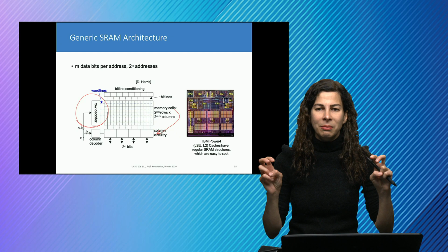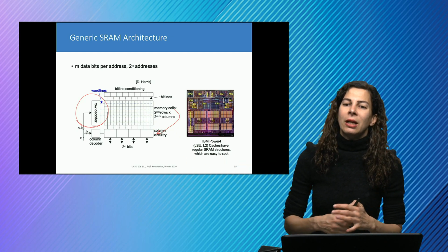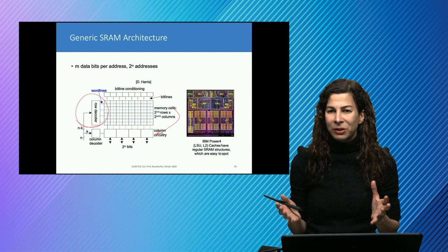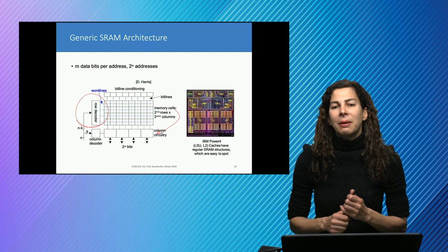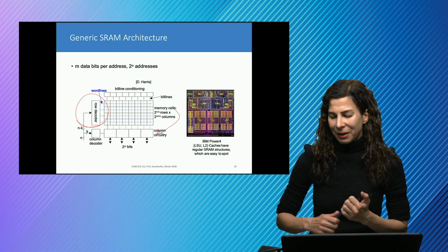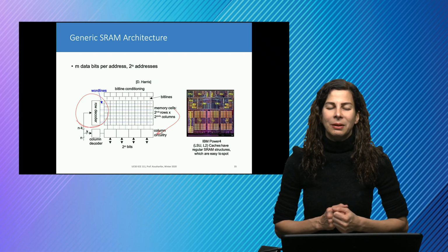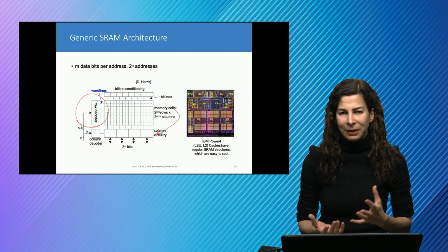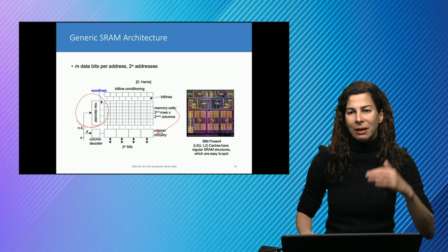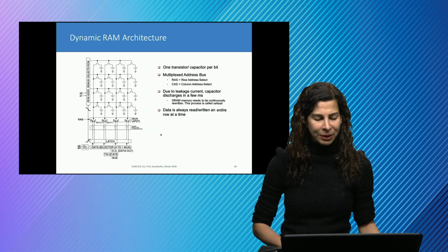The memory hierarchy means that we have main memory, which is much larger. In terms of FPGAs, it could even be off chip because we may not be able to handle so much memory on the chip. But we also have SRAMs that are not as small as DRAMs, but they can offer caches for us, for example, and then we may have registers and even multiple levels of caches that correspond to different SRAMs with different accessibility.